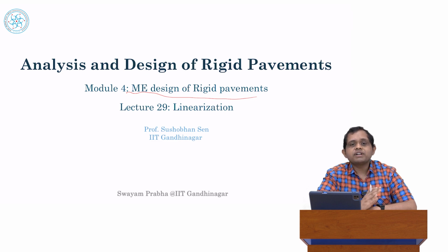It's only through fatigue theory that we can actually see some damage or cracking or distresses occurring in rigid pavements. LRFD does not actually give us any such thing. So the LRFD theory does not, strictly speaking, apply to rigid pavements. So we saw how we can apply fatigue theory, which essentially comes down to something called an SN curve. That's sort of a constitutive model from a fatigue theory perspective.